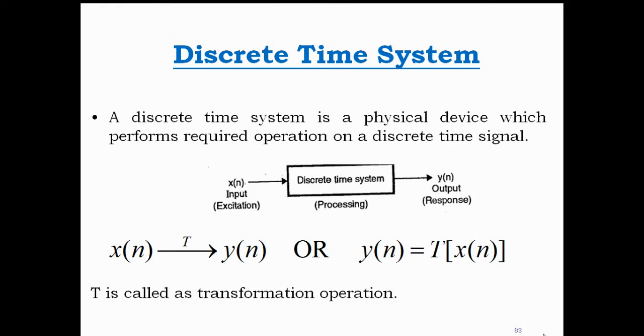In order to make these operations happen, the condition was that whatever two signals you wanted to add, both must have the same number of samples, or the same length of sequence. If not, then we need to add some number of zeros at the right side or left side to make both sequences the same length. That process of adding zeros is known as zero padding.